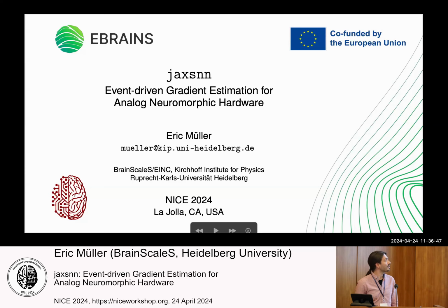I don't have any reminder on the BrainScales hardware system, so maybe just a sentence about it. We have several generations. The latest generation of the system is a mixed signal system. We have analog neurons and synapses on it, around 130,000 synapses on one chip. It's accelerated, so we typically have neuron time constants in the range of microseconds, and it also has one particular feature, which is programmable plasticity.